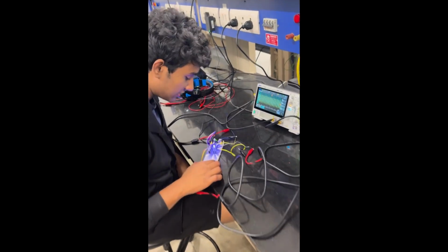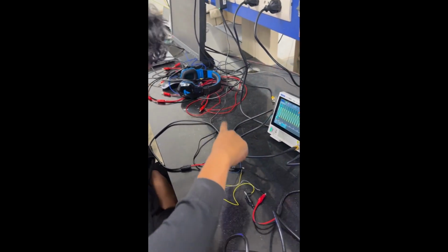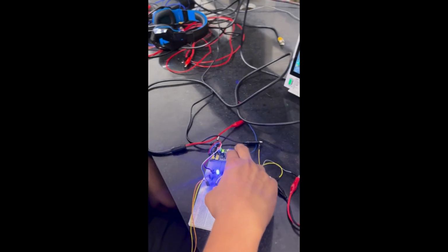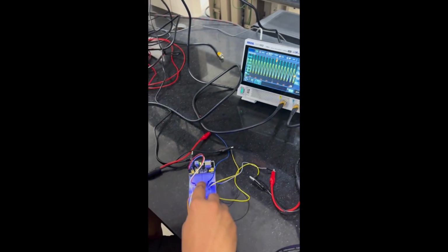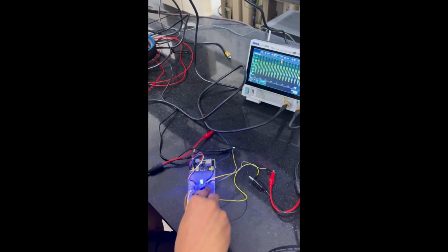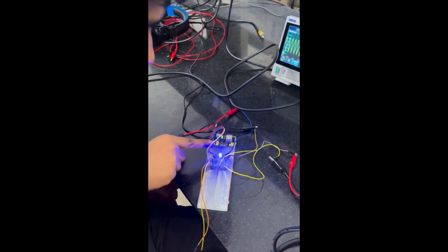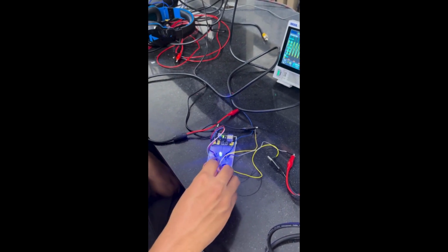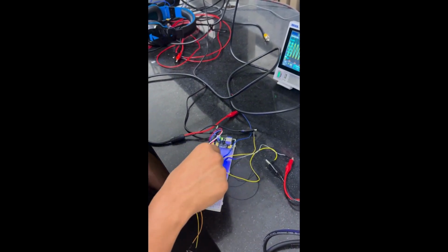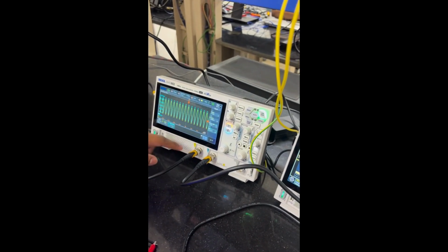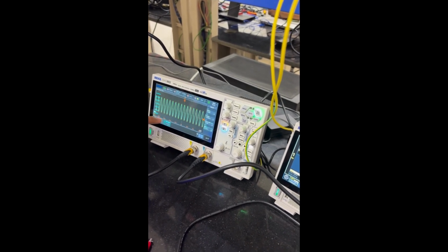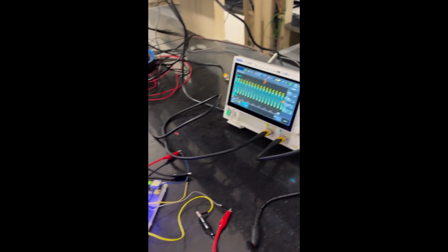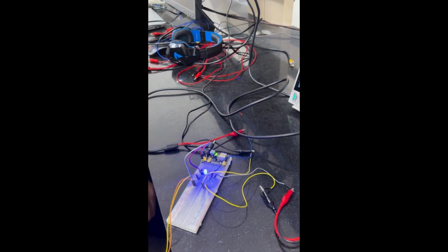This is our photodiode setup. We have the power supply coming from there, and the input is in channel 1. We have an LED, a 330 ohm resistor, and in channel 2 we are obtaining the output, a photodiode and a 10k ohm resistor. The photodiode is connected in reverse bias so that minimum current passes through it. If we block the light coming to the photodiode, as you can see, the voltage decreases drastically, because the more light passes, the more voltage is obtained.